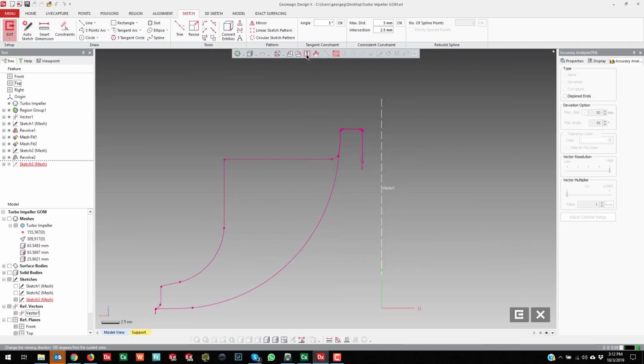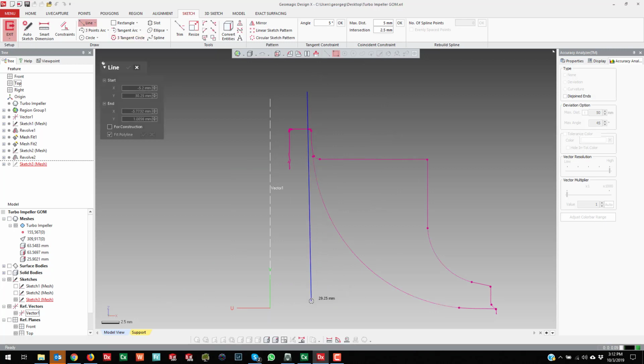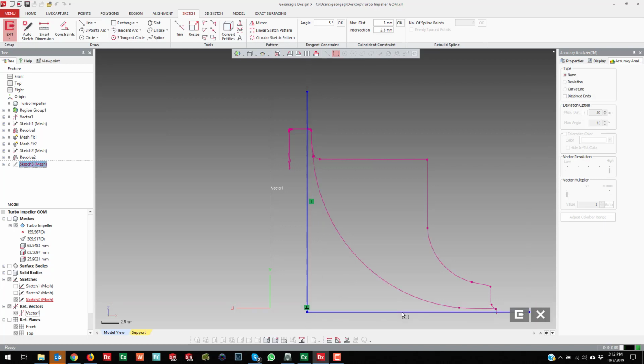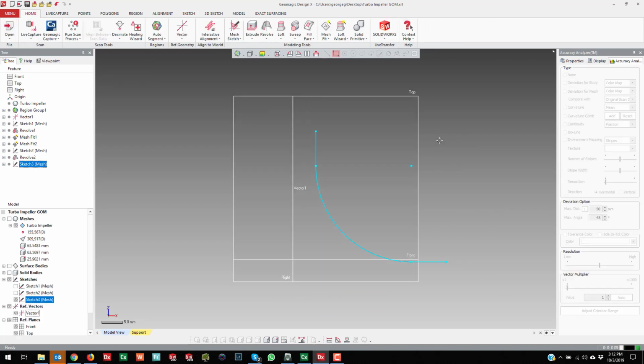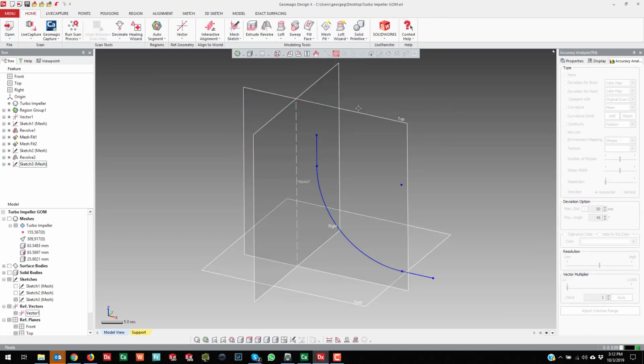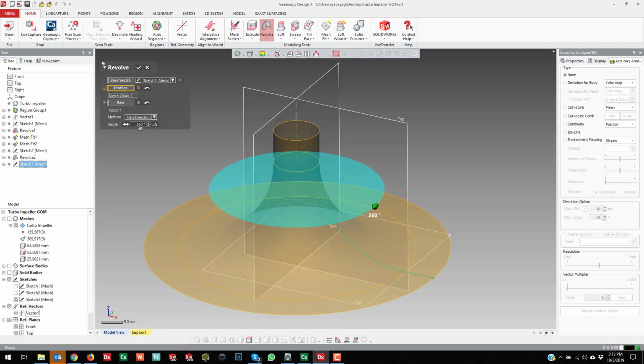And if my sketch ever flips the direction, I just feel more comfortable this way, I can do that. So if I just draw like that, draw these, move those into position, make sure it's inside of the material, and then we'll do a giant fillet here. There we go. And the reason why I use this method instead of the offset method is because sometimes when I use the offset method, the surface trim struggles when it's 360. So remember when I said don't go all the way around here, 180, and I'll just do like 10.